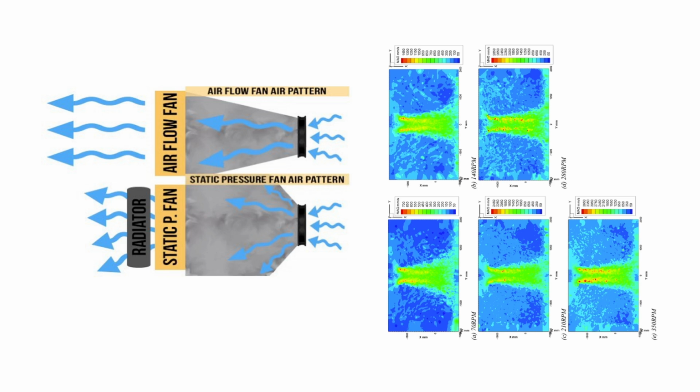But if you're using it at the front of your case for a good air cooler, you do want a good concentrated airflow so that the air can get to your CPU cooler. So, a little bit of explanation of how a fan works. It accelerates the air through it. It pulls a small vacuum in front. So you do want a good high quality fan to supply this fan with air so it fills in this vacuum as efficiently and effectively as possible, improving the overall efficiency of the CPU air cooler fan overall. And this will drop your CPU temperatures or potentially noise levels by a little bit.